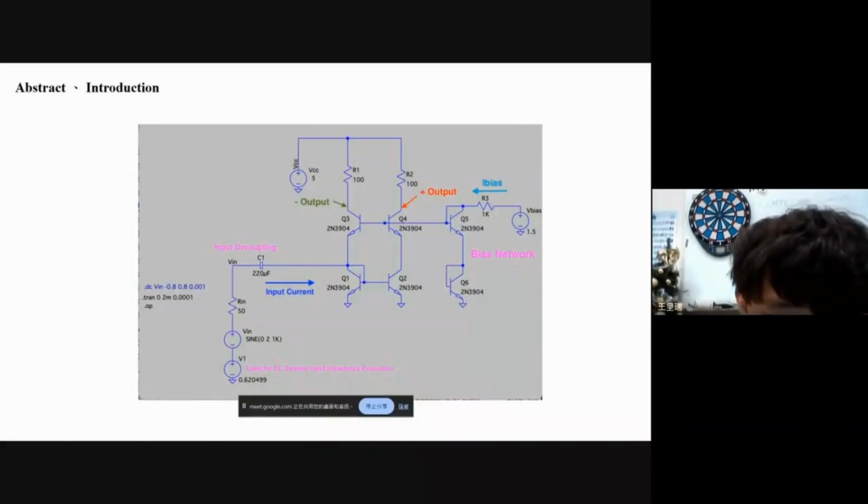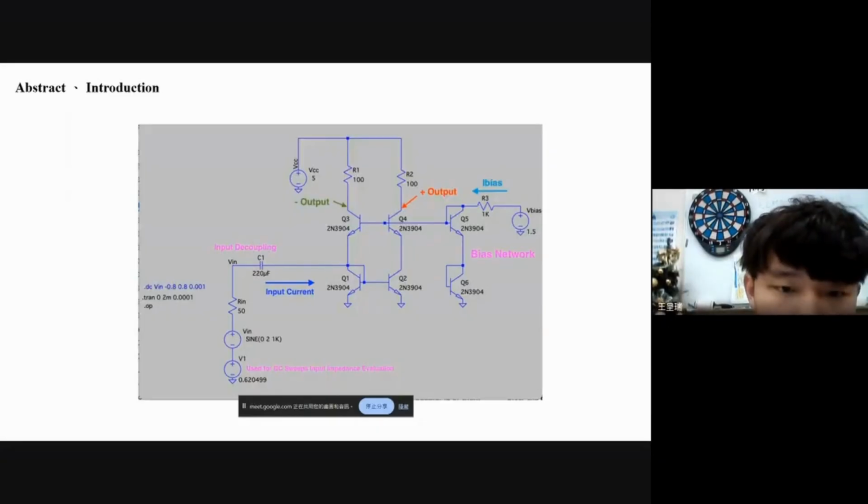When the input signal is large and positive, input current flows mostly through Q1, which acts as a transconductor and the cascode device, and Q3 becomes cut off as its emitter voltage rises. Q2 mirrors the Q1 collector current through cascode device Q4, which sees a replica of the large positive input current as the positive output.